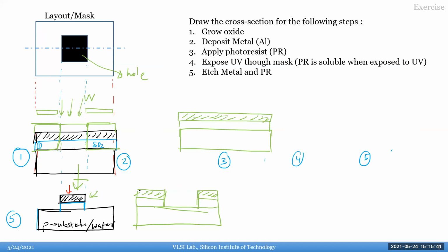And that's something decided within the foundry design rules. So when they give you a device and they say these are the set of masks you need to do, those are all preconceived. You don't tell the foundry to do a negative mask here. The foundry has figured it out. All they ask you to do is: wherever you want metal, you draw this; wherever you want diffusion, you draw this layer; wherever you want poly gate, you draw this layer. And the negative and positive is done by that.